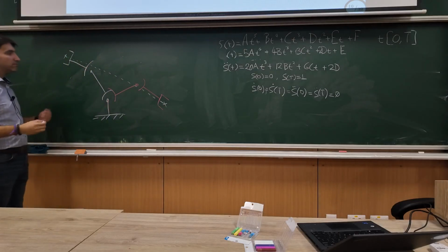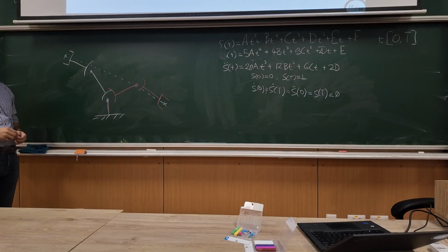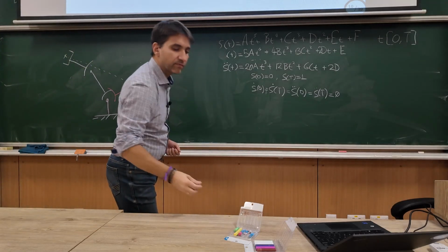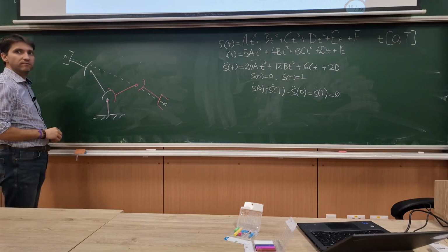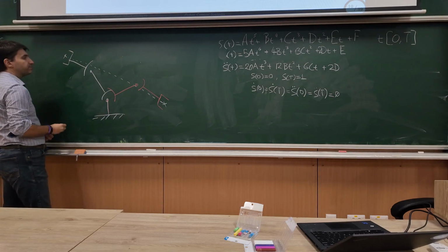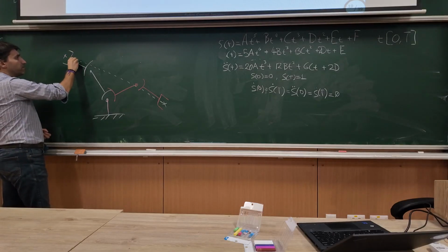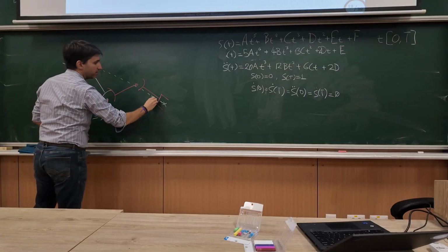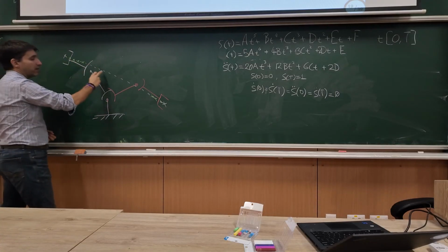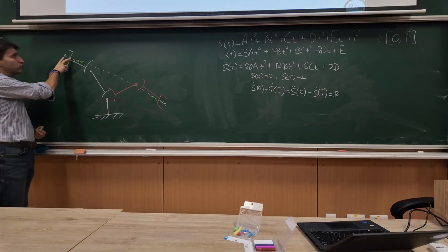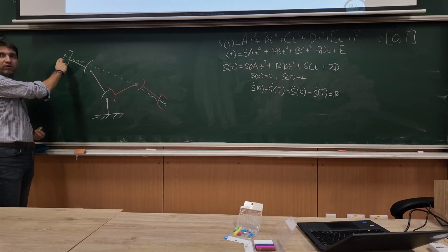And then I choose a step, like how many intermediary positions I want. And then for every position I calculate the inverse. So basically, I take this trajectory and I sample some points on this line. I have to choose what is the distance between the points I will take.